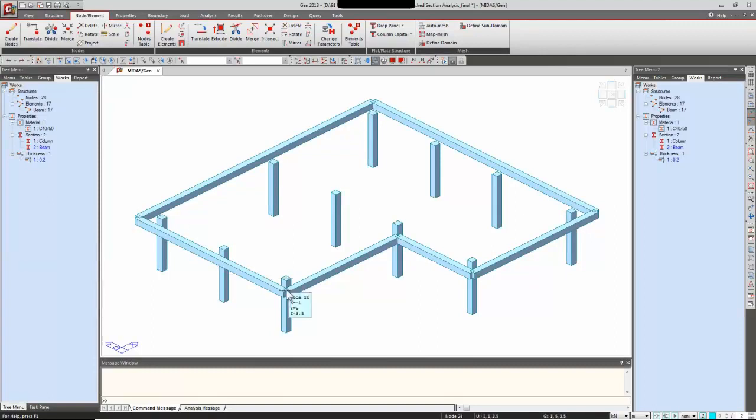Okay, now before we go ahead and create the mesh slab, we will do some modifications. Over here in the workstream menu, as you can see, the number of elements and the properties that we have defined are displayed. The material property has already been assigned to all the elements. The column property has also been assigned to all the elements. So we do not actually want this column property to be assigned to our periphery beams.